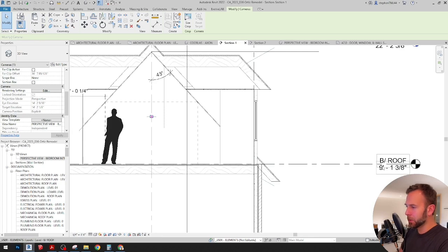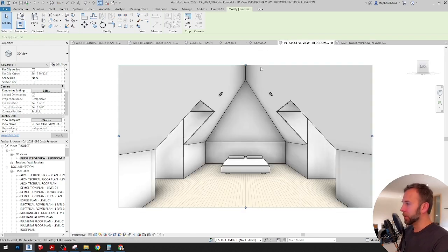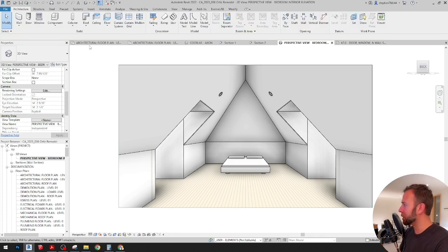So if my floor plane is at, we'll just say 9 feet, I'm gonna have to add, so if we're at 14, that's 5'2". That's okay. That's kind of a normal eye height. Around 5 feet is pretty good. So if I wanted to get a little more height, I can lower the camera, but this is good. Let's just send this through.